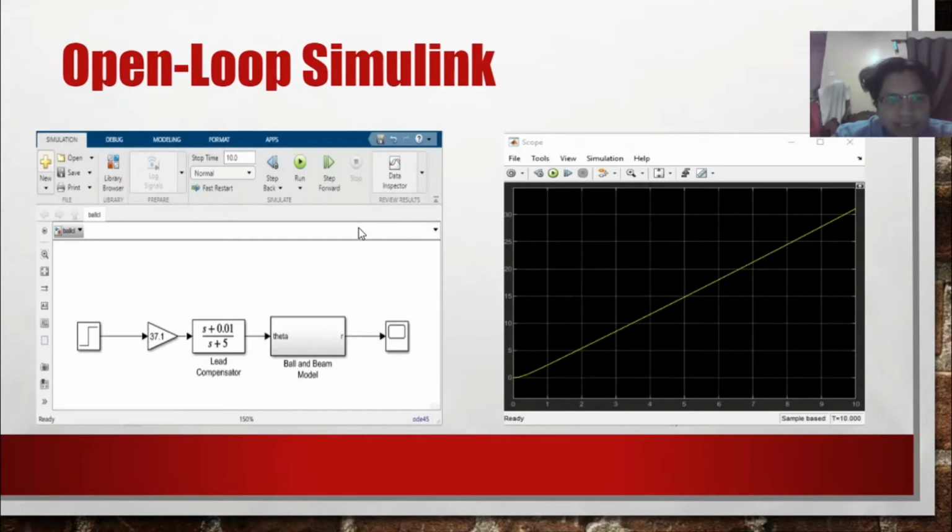This is our open loop Simulink. The control system in open loop control is meant to be the inverse of the plant. The most significant disadvantage of an open loop control system is that it is completely reliant on calibration and is unable to adequately cope with external disturbance. This is our open loop Simulink, and on the right is the response.